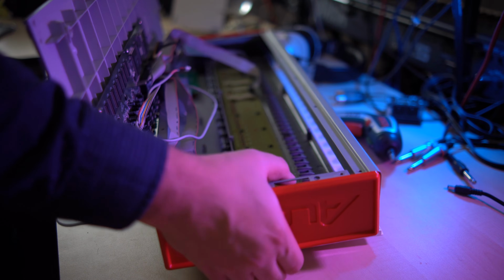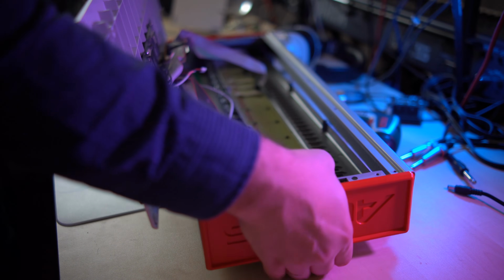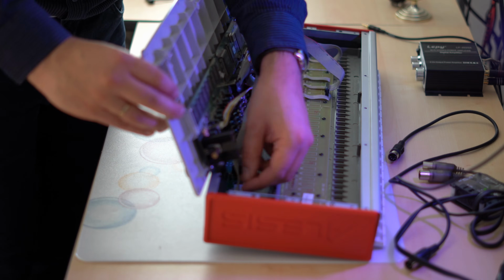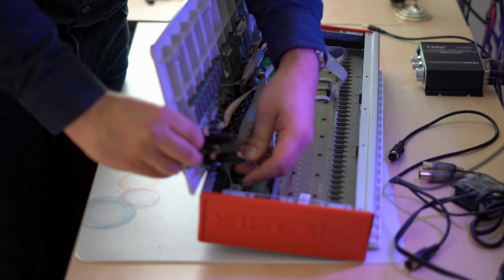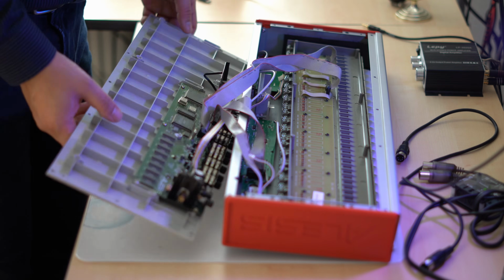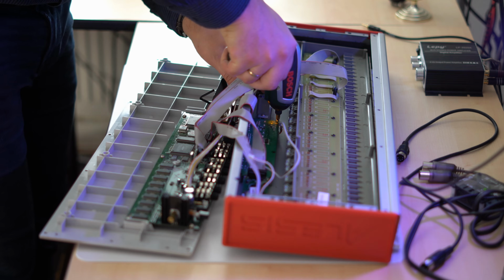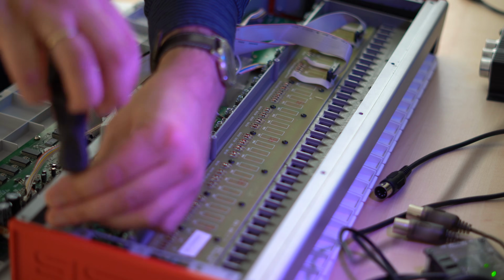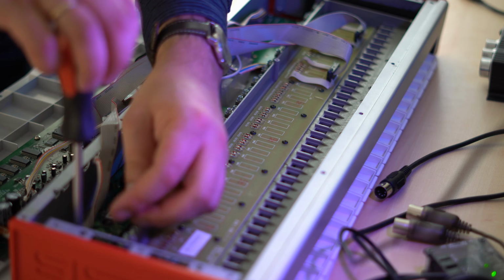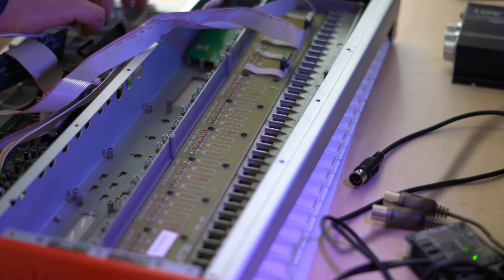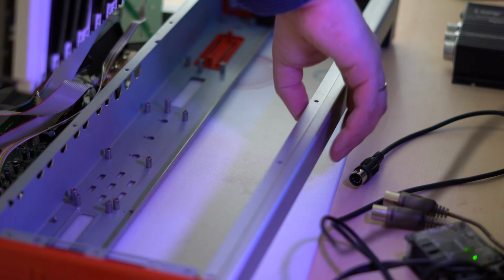Nevertheless, it's a very good idea to take photos of the process, so you can look up where each part belongs later. You should now unplug the LCD power connector from the mainboard, and after that you can put down the bottom lid onto your desk and start removing all the screws which attach the 4 PCBs to the case. And once you removed all the screws, you can then just pick up the PCBs, reconnect the LCD and put away the case.